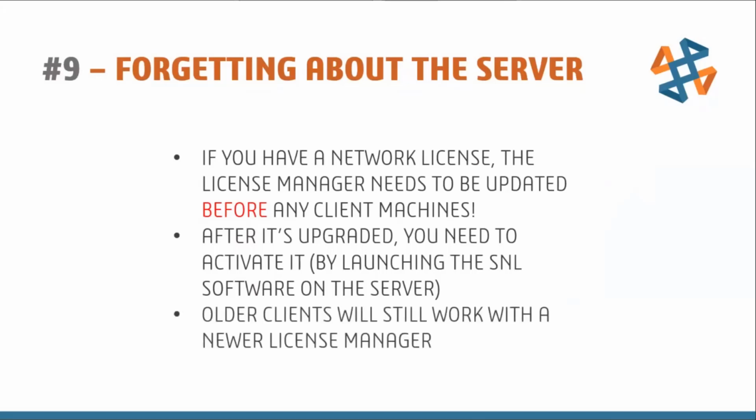That worries a lot of people, though, because, okay, does that mean it's version specific? Kind of, but older clients will always work with a newer license manager. So it's backwards compatible. Upgrading your license manager is not going to affect anybody that doesn't upgrade. So that's a usual question, right? If I upgrade my license server to 2020, does everyone have to get on 2020 immediately? And the answer is no. You can stay on any older version. You could use SOLIDWORKS 2012 with a 2020 license manager. There's no issue there.